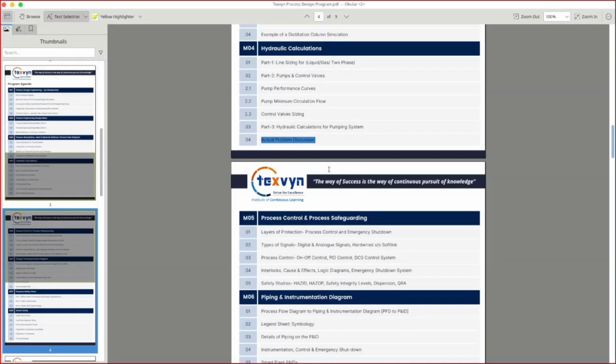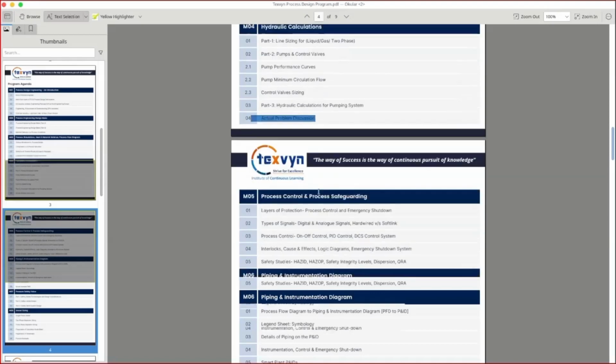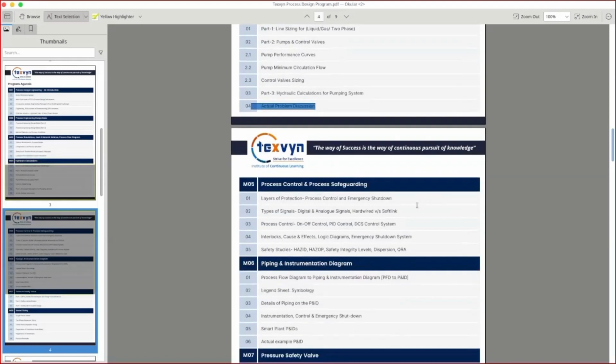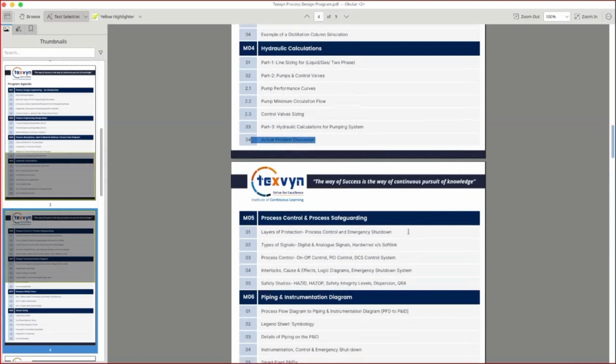Here in this case, the feed pump will be a single destination, because the feed pump will only deliver the feed to the distillation column. So it will be a problem with one destination. And the reflux pump will typically be common for reflux as well as the distillate product being sent to the storage. So this becomes a multiple destination problem for centrifugal pump hydraulics. So in these two particular examples, we will cover two different types of systems which are designed for pump hydraulics.